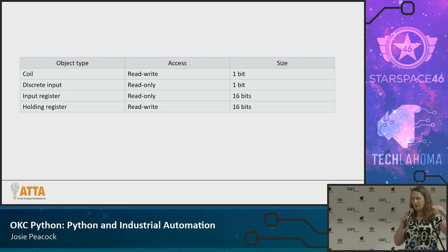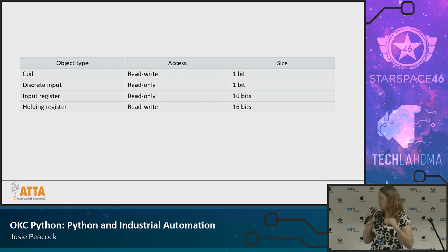You have coils and you have registers. Each of these coils and registers has an address that you actually have to call up. And you have a slave address, which can be slave 1, 2, 3, 4 in Modbus RTU, or in Modbus TCP you're using a client-server model, which means you just call up that IP address, and then you get that information from the registers.